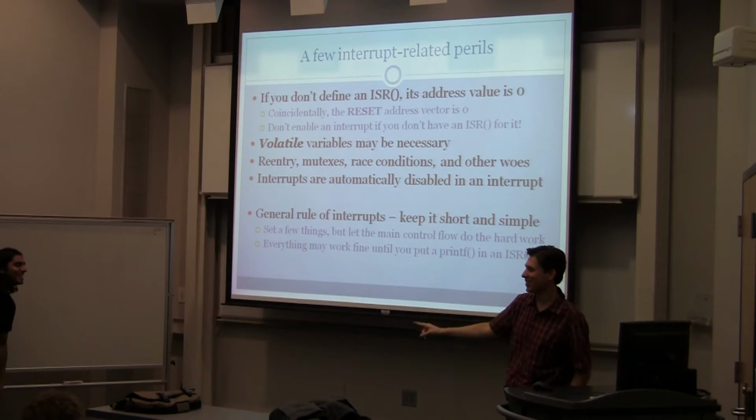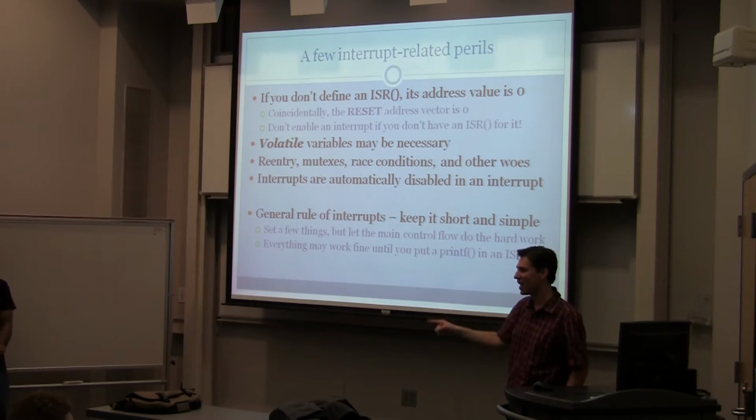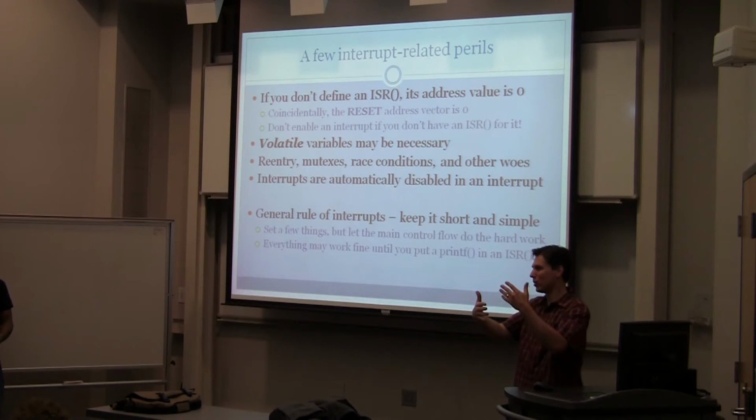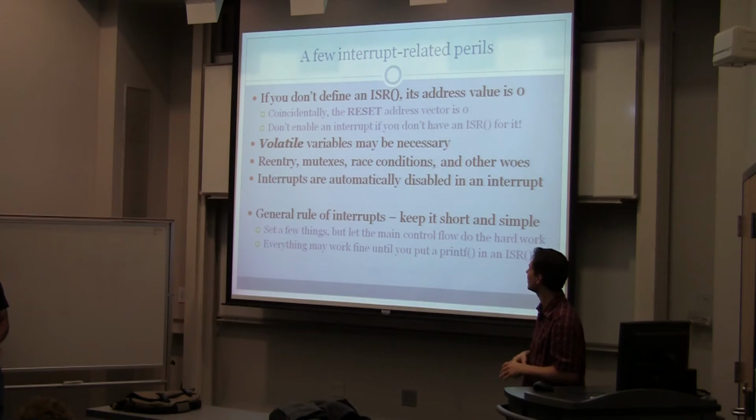Yes, so next. Now there's one caveat to what Cross just said. An interrupt cannot happen when you're dealing with another interrupt. So you could miss an interrupt, or usually what happens is they queue. You have an interrupt and then the next one happens right after that, but it may not be perfectly timed if you want it.